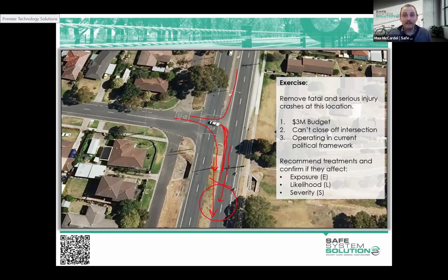Compact roundabout. That's very interesting. So I did say that we couldn't do the normal roundabout because that's going to be too expensive, because it's going to involve lots and lots of land acquisition because it's a large footprint. Compact is making it a much smaller footprint, and I've got an example in a few slides that is going to talk to that point. Let's see what else we talked about here.